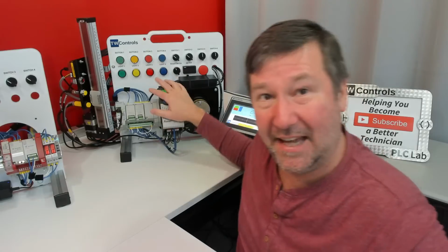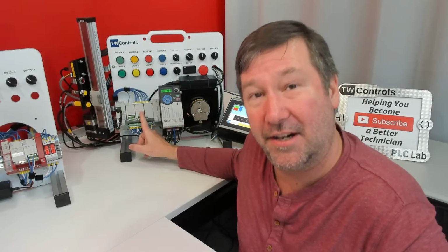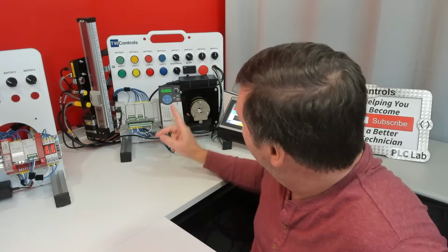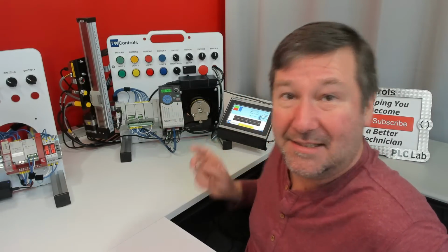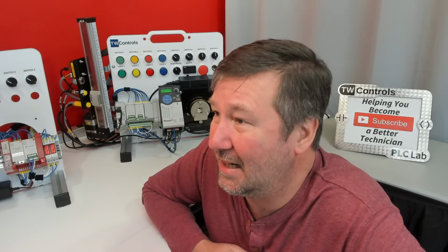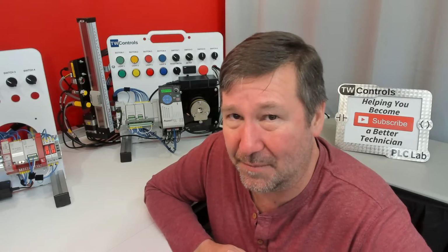Especially in this case, though, I have the Micro 800 that needs Connected Components Workbench. I have the PowerFlex 525 that needs Connected Components Workbench, and the PanelView 800 that needs Connected Components Workbench. So sometimes it's just for more of uniformity. Again, starting out, there are plenty of HMIs that have free software. Like even you that was just asking that. I mean, that's going to be a paid software, and you can buy this PanelView for less money than the software would cost. So yeah, it all depends on what capabilities you need.